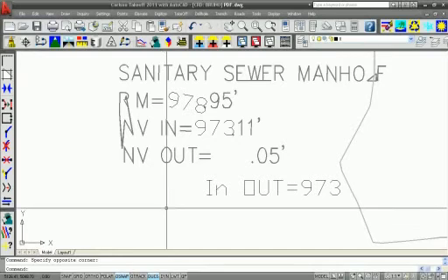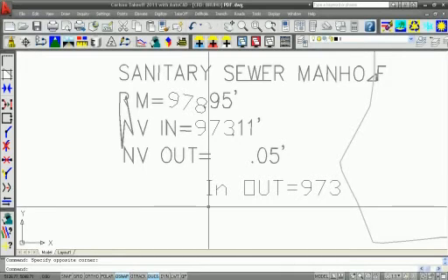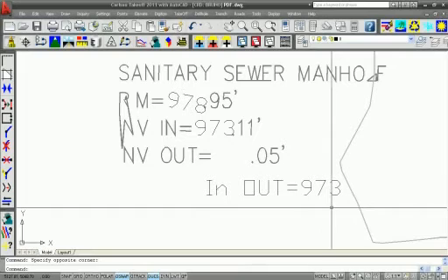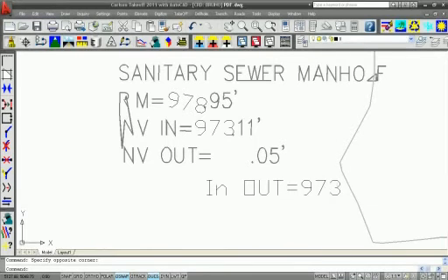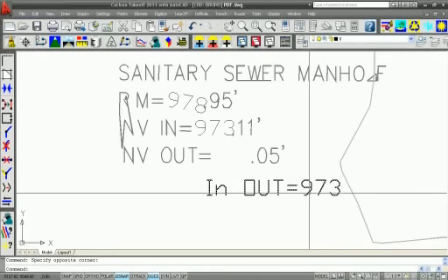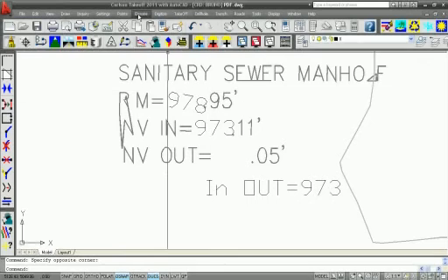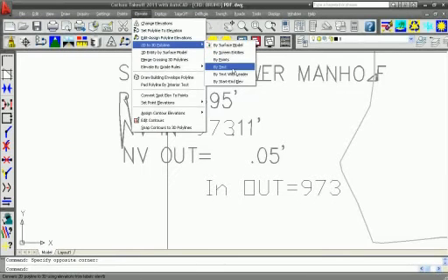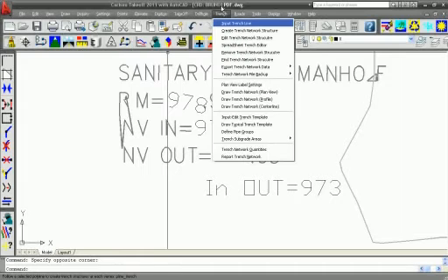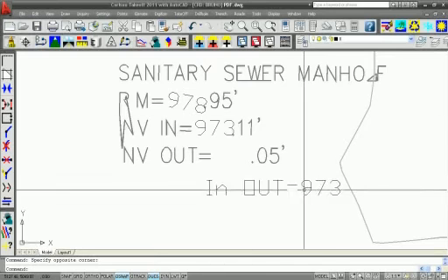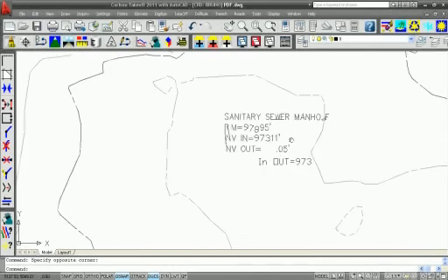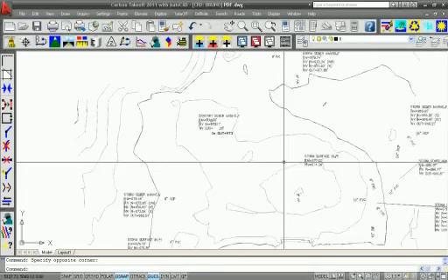and also our elevation tool. So, yeah, say we had a lot of leader lines for a 3D line or a curve, we could convert all those leader lines into actual text and then run elevate 2D to 3D by that text. Whereas before, that line work would just be dead to us. So we now have the ability to work off of that line work and convert it in the drawing.